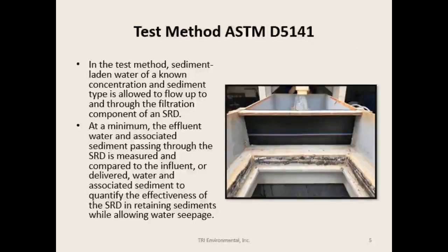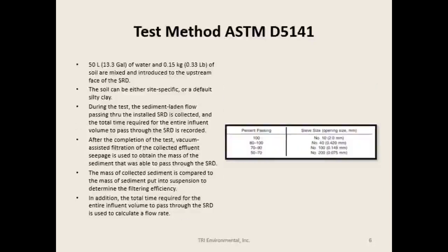Test method ASTM D5141 quantifies the ability of an SRD to retain sediments carried by flowing water under bench scale conditions. 50 liters of clean water and 0.15 kilograms of test soil are mixed together and delivered through a valve to the upstream face of the SRD. The default soil mixture is described in the table.